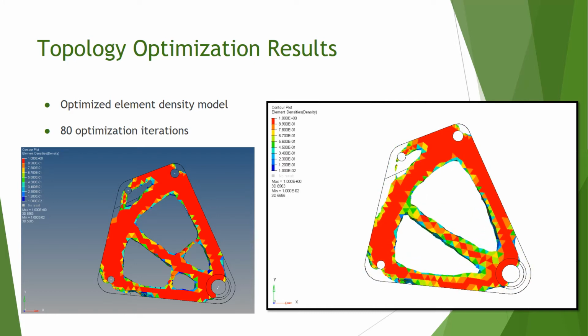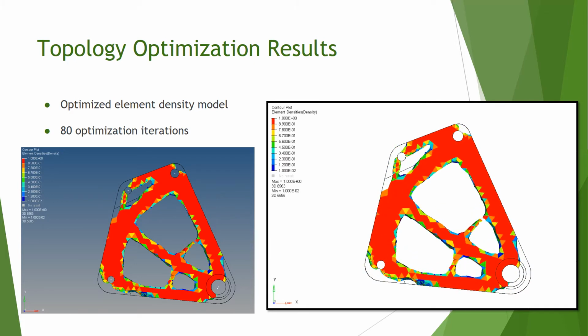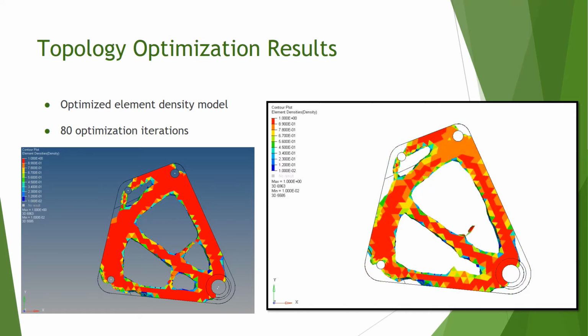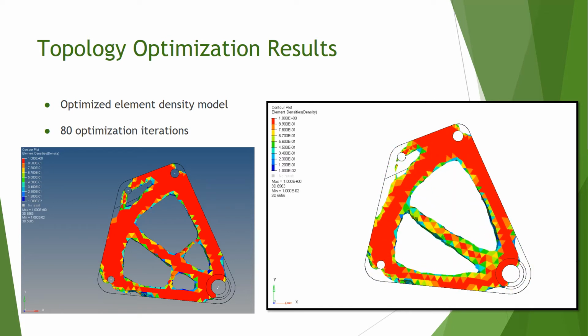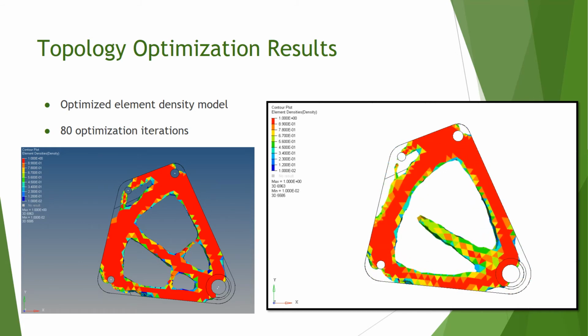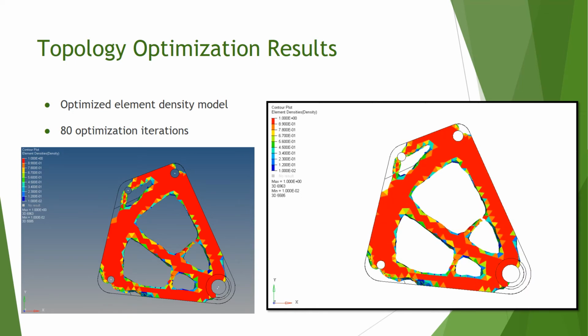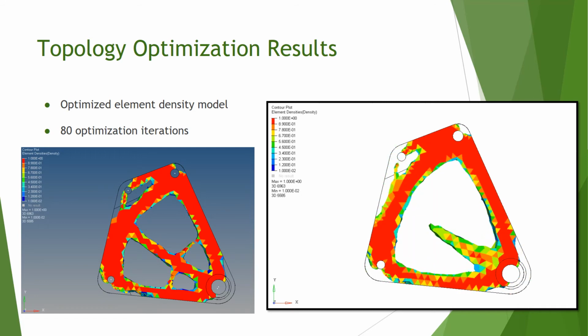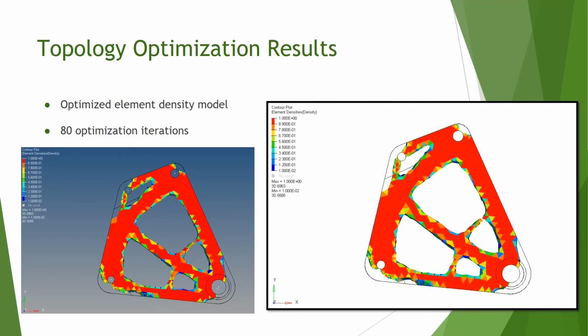Interesting features that come up with the optimization are the triangulation of the top arched portion of the rocker to the location of the pressed-in bearing, and in the last solution iterations, there are small webs extended from the middle triangulation to the outer two regions of the rocker. These could be crucial for the rocker's performance in buckling, and it'd be interesting to run a buckling analysis with and without these extra parts.